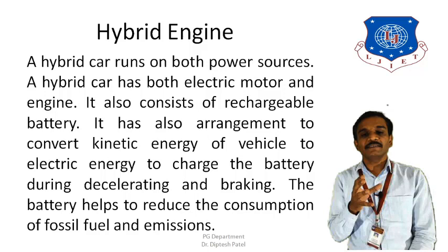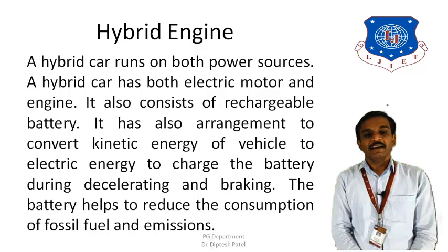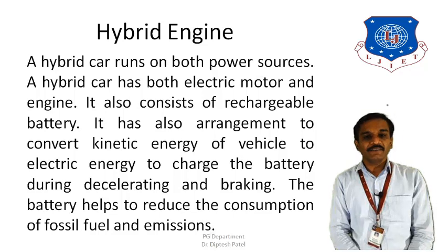The battery also gets charged during the deceleration and braking of the vehicle. That is done with the help of the alternator, in which the kinetic energy of the vehicle is used. Especially when we are decelerating or braking, we do not require the momentum that the vehicle has, we are trying to reduce that momentum. So that kinetic energy would be converted into electric energy, because otherwise it would be wasted, and in fact it would improve the braking efficiency of the vehicle. So the rechargeable battery can also be charged during the deceleration and braking of the vehicle.